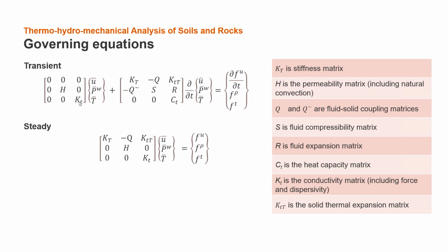And moreover, with the water content changing, the thermal property can also change depending on the thermal model that we use. Also, the permeability matrix H and the compressibility matrix also include the function of temperature, of permeability, and water contents.